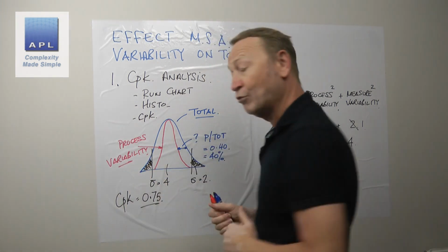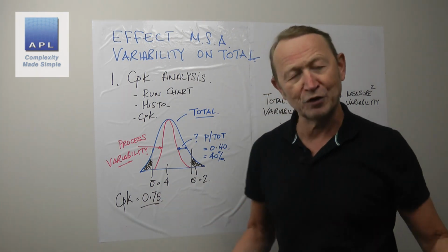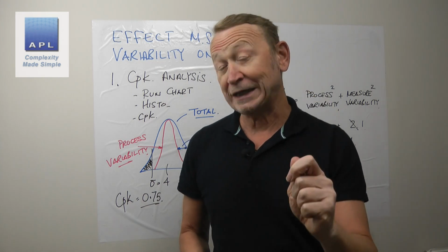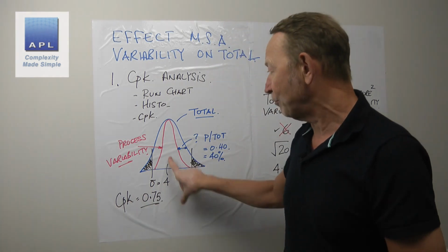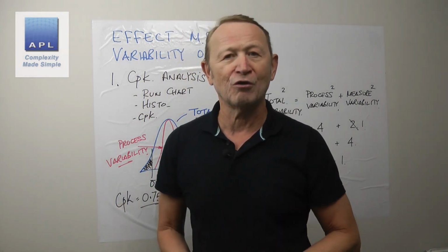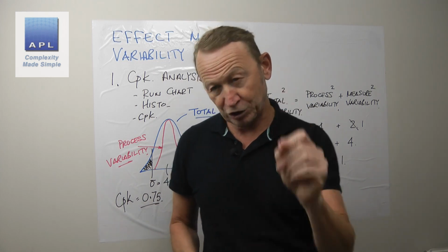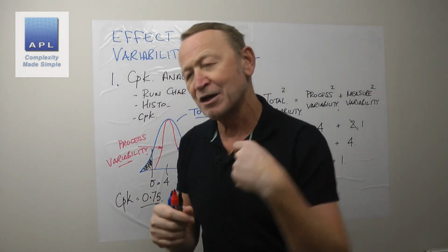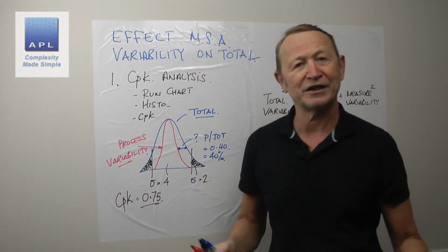Measurement variability always inflates the result, and if it inflates it enough, it's worth attacking it to improve your Cpk. It's part of your Cpk solution potentially. But of course, really, what you want to do is, if you do new product introduction properly, you shouldn't launch a product like this. So all of this should be tidied up when you do your PPAP and things like that at your new product introduction stage. What you should do is do this analysis, understand the lack of capability, put controls in place to get capability, and get rid of all of this nonsense before you get a problem.